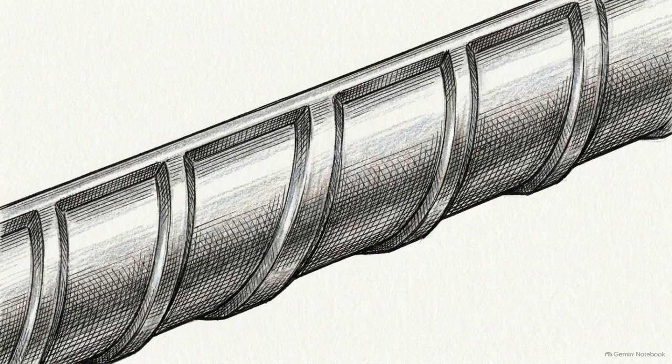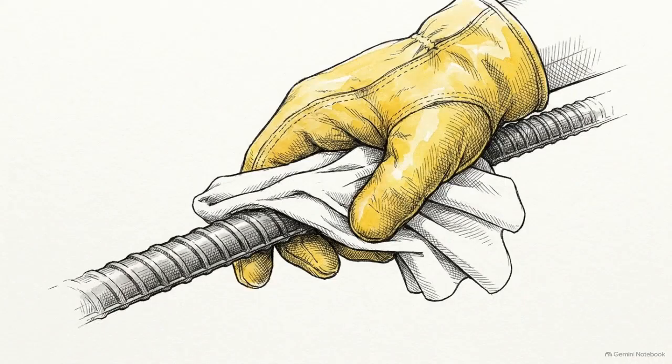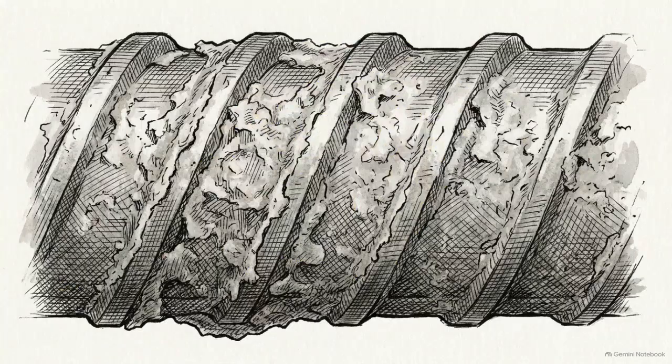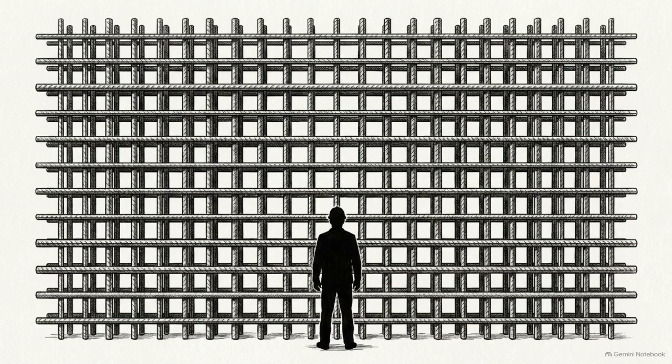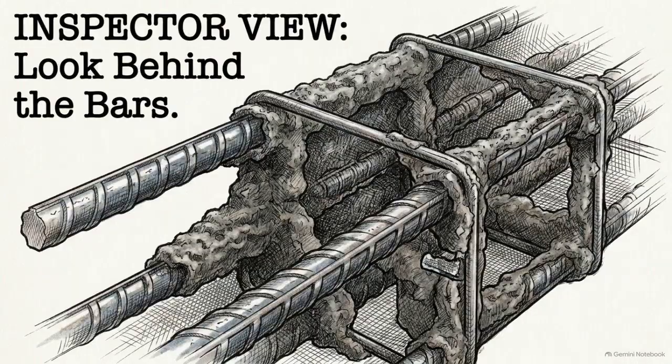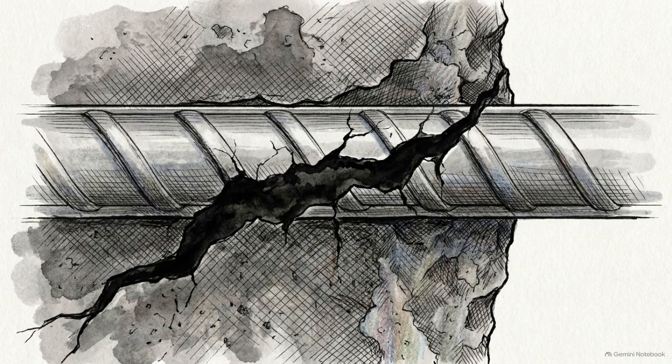Rigidity is only the first requirement. The steel must also be clean. All reinforcement has to be entirely free of materials that inhibit the bond before placement begins. Hardened overspray on the face of the reinforcement is a critical defect. Once dry, it actively blocks new shotcrete from bonding directly to the bar. You cannot evaluate this cleanliness by standing directly in front of the wall. The inspection requires walking completely around the cage, checking corners, forms, and the hidden backsides of the steel where overspray accumulates. Evaluating cleanliness solely from a front elevation guarantees that hidden defects will remain undiscovered, permanently compromising the structural bond.